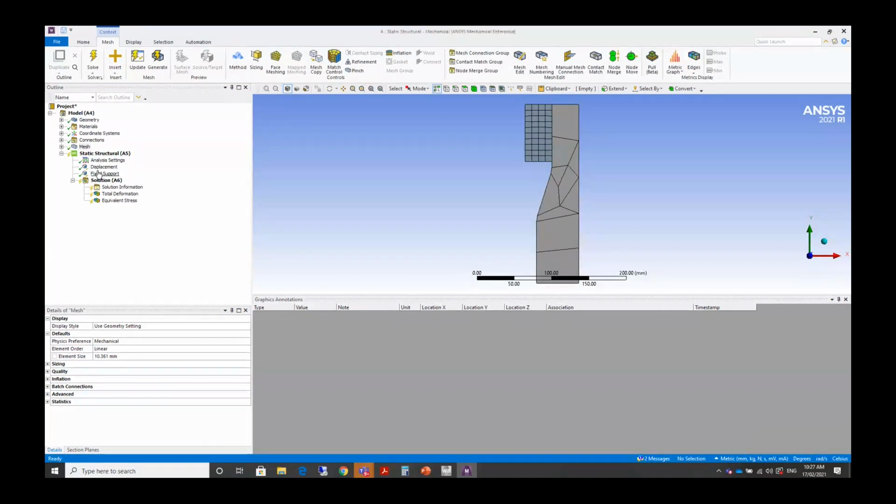Okay, someone's asked, can one obtain similar results if you analyse only the block with the hole and add a force reaction? You could, but when you do that, you don't know what the angle of contact is. Depending on how hard you pull down on the pin or pull up on the housing, the angle of contact is going to be different.